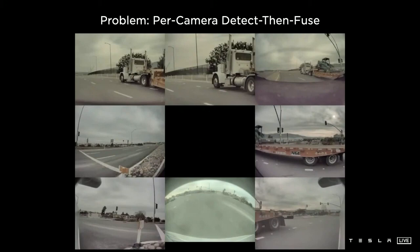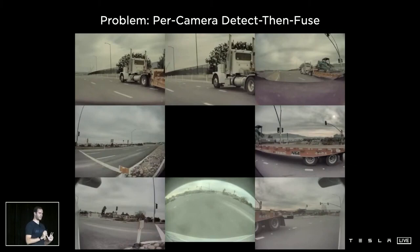The other problem with this, by the way, is also for object detection. If you are only making predictions per camera, then sometimes you will encounter cases like this where a single car actually spans 5 of the 8 cameras. So if you are making individual predictions, then no single camera sees all of the car. Obviously you're not going to be able to do a very good job of predicting that whole car, and it's going to be incredibly difficult to fuse these measurements.